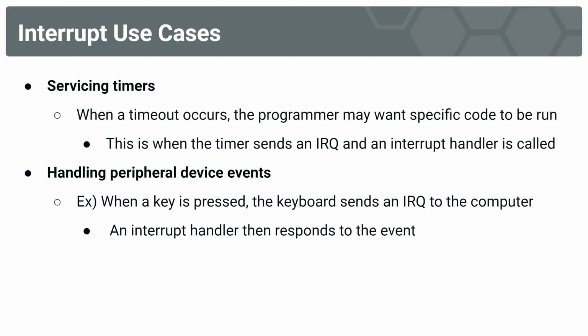So here are our two common interrupt use cases. It'll be servicing timers. So when a timeout occurs, the programmer may want specific code to run. When the timer does this, it'll send an IRQ, and then the interrupt handler is called. And our other situation would be handling peripheral device events.